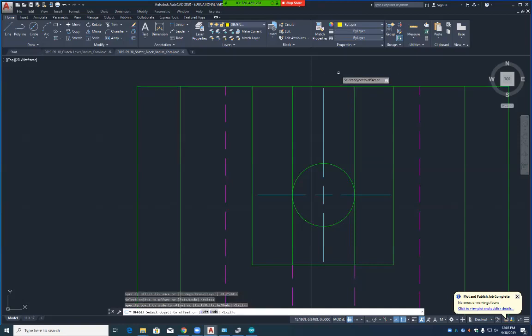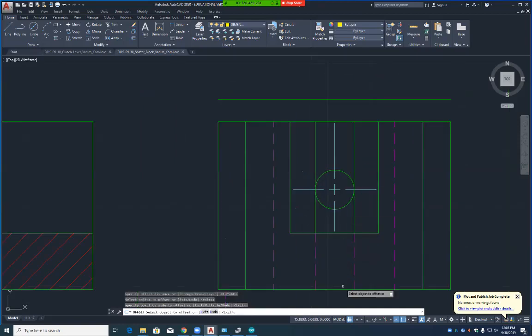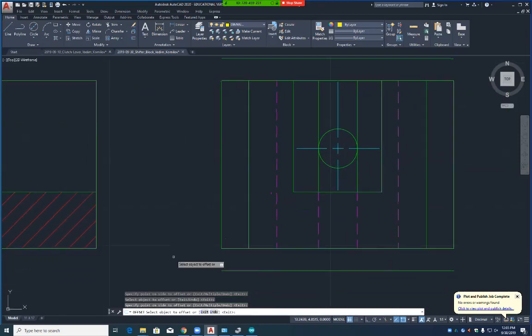But the hardest thing students have to grasp is it's a ½ inch away from your cutting plane line, if you have a cutting plane line. Okay? And like you said, it doesn't always work. If you want, you can just offset this line a ½ inch, if you wanted to get exactly ½ inch away and just give yourself a line to go to. You can always do that too.